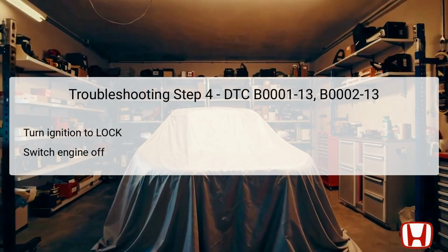By switching off the engine, it safeguards not only the technician, but also the integrity of the airbag system components. Please take care to wait until all dashboard indicators have dimmed off completely, confirming that no additional current is flowing to the circuits linked to the airbags. At this point, you are preparing to perform further disconnections, ensuring that no unintended operation occurs.